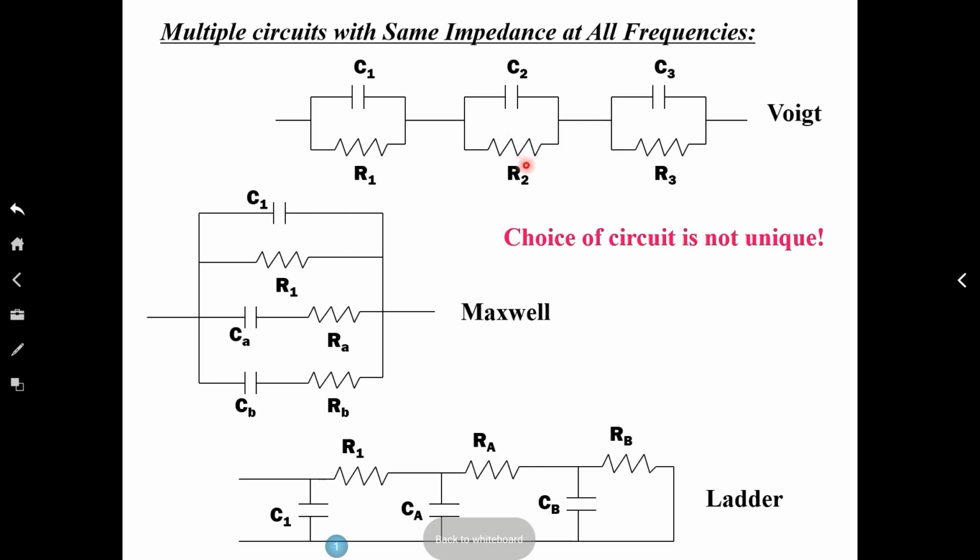You say, I can make changes in my sample that will have an impact on individual parts that I can relate. For example, if you take your YSZ and sinter it at different temperatures, 1200, 1500, 1700, you get three different ratios of grain to grain boundary, and you should see the impact on the grain boundary component.